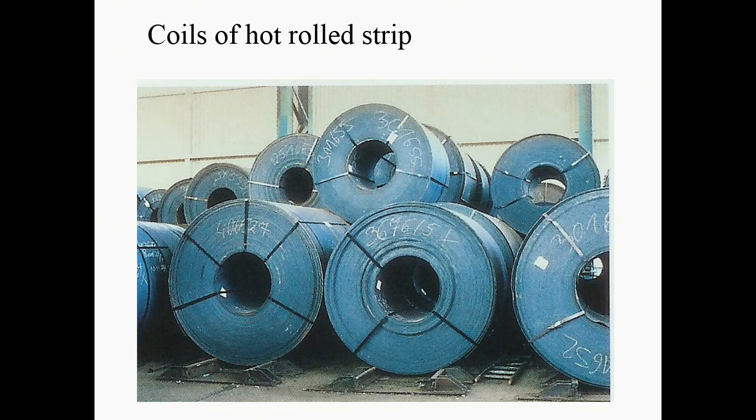Now they will have been corrosion protected by the steel supplier. They will have been phosphate treated and they will have been milled, but you cannot stop them from rusting, particularly where they contact the supports and things at the bottom. So you're going to get bits of rust, bits of dents. You can see here, there's a dent, and there's here a dent. There are all these wrinkles that are introduced. This is a material that you've got to handle, and you've got to deal with all of these issues that have been from the storage and manufacture.